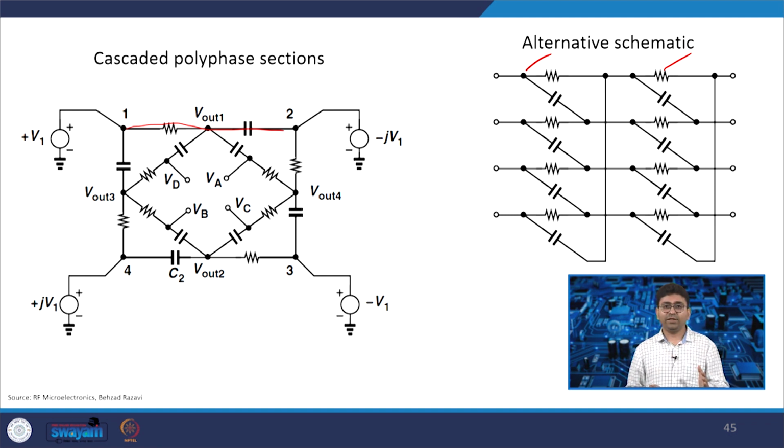And what is the advantage of this? In simple terms, if we consider only R1 C1, it has a very limited bandwidth. However, we can improve the rejection bandwidth by adding cascaded stages, but it also has some disadvantages. If there is more variation in R and C, the image rejection ratio throughout the band will not be constant, and because there are more RCs, a loading effect also comes in. You need to consider that while designing multiple-stage polyphase filters.